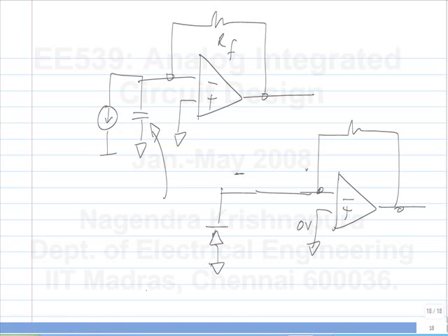So maybe what you will do is put the bias voltage here, and for signals, you ground it. I can use a different value of V bias here, right? For the largest current I expect, I can adjust the V bias. So that is not a severe problem. You have to be aware of it, but it's not a severe problem.